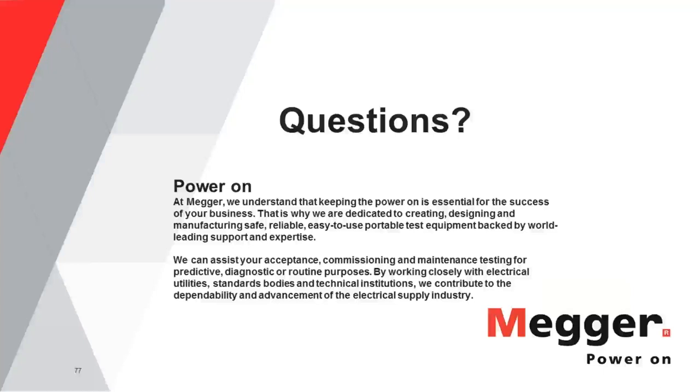And I think IEEE's on the ball with this. The 5 gigohm value, like all of these things, is somewhat arbitrary, but it's arbitrary in the right direction. And as a general rule, I would follow that. PIs are very reliable and a very good test when you're down into the megohm range and in the low gigs. But once you get up above that, the number itself becomes so overwhelming in importance that that's what you want to work with.